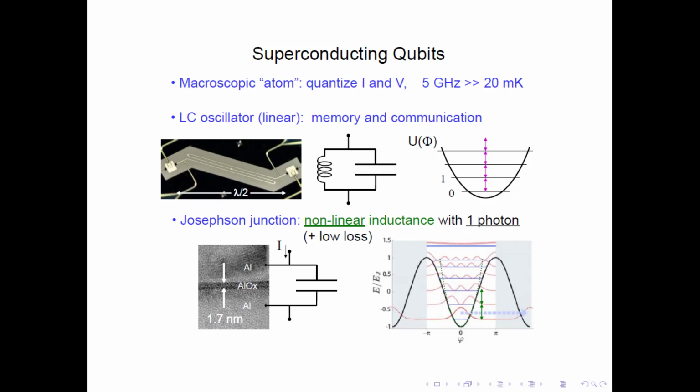And this is also important to recognize the Josephson junction as nonlinear inductance. That's one of the interpretations that can be grasped. I will move to that interpretation a little bit later. Basically, you have, technically speaking, a nonlinear potential, which constitutes the washboard potential. In an ideal harmonic potential, you have equal distance between energy levels, and in the case of anharmonic potential, this distance is not equal anymore.